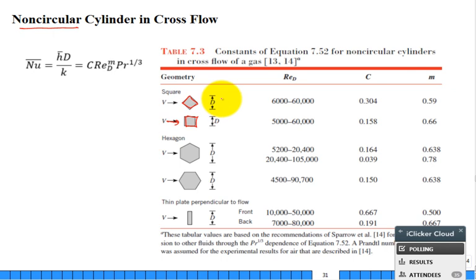You use this for the length scale and the Reynolds number, or you use this in the length scale, the Reynolds number. Aren't they different? Well, D is D, but look, it's from tip to tip or the middle of the side to the middle of the side. They are a different length scale. Good for this range of Reynolds number. This is your coefficient, plug and chug.